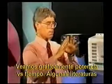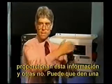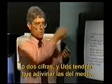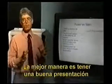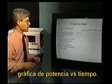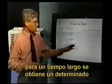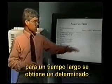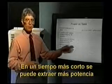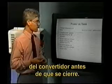Let's take a look graphically at how we might look at power versus time. Some inverter literatures give you this information, some do not. They may simply give you one or two printed numbers, and you have to guess in between. The best approach, I think, is to have a nice graphical presentation of power versus time. What you notice in general for all manufacturers is that for a long amount of time, you get a certain continuous rating of output power. Over a shorter period of time, you can extract more power from that inverter before it shuts itself off.